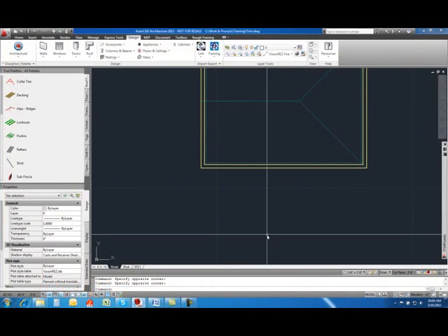We will be talking about trim, and specifically custom trim, on the fascia of the roof. When we make a custom piece of trim, there are lots of different factors that we can draw in there, but the most common one is the shape of the trim. With that come a couple of issues we have to keep in mind, namely the insertion point of the trim profile that we make, as well as the orientation of that profile.